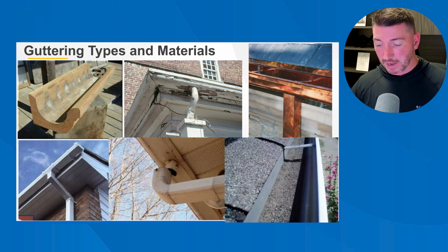Are there any gutter spikes backing out? Can you see signs of leaking from the joints? Right? You're going to see water sort of pooling up on the underside, and then there's going to leave stains on the bottom of the gutters. So you can see near the seams if there's any leaking going on there.